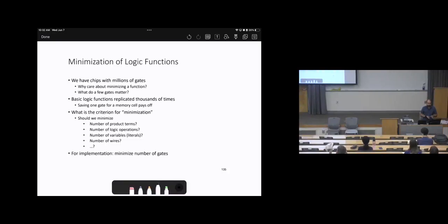We realized that dealing with this will be tough and may not be unique. After that, we looked for a way to make it unique, so my representation will be the same as yours and the same as other designers'. Then we found that canonical forms are a great way to represent this because they are unique, even though they do not minimize the logic gates.